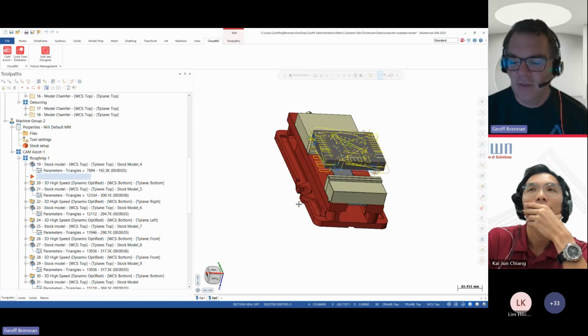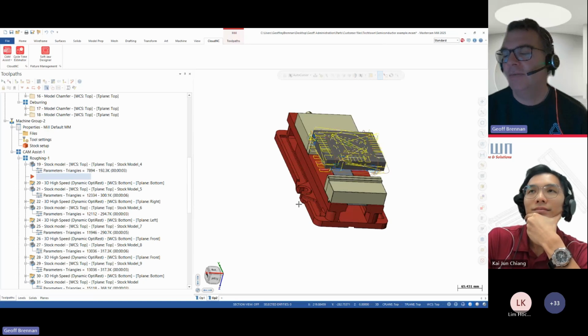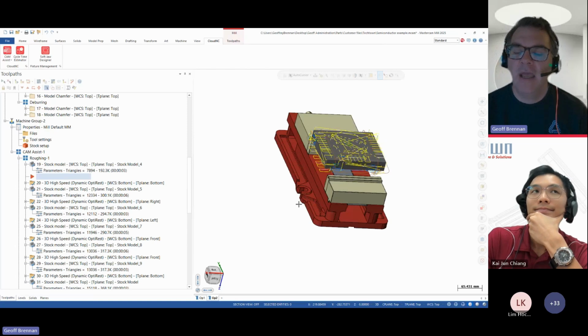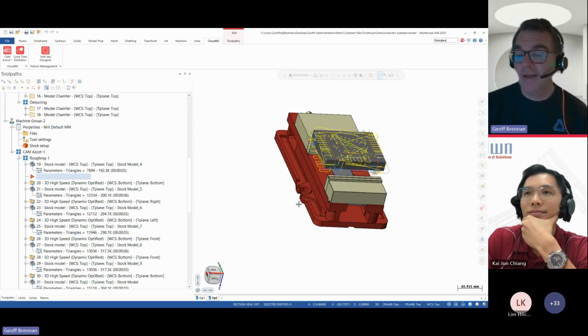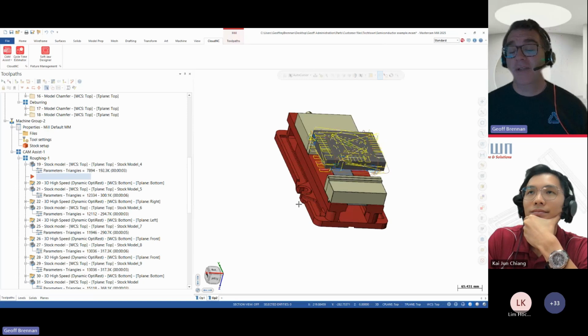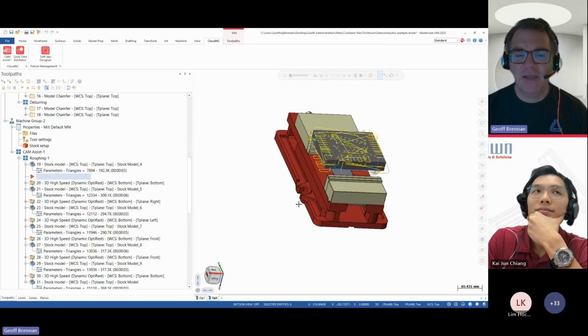But in terms of the size that CAM Assist can handle, the dimensional constraints in the computational space are a bit limited to sort of 0.5 meter by 0.5 meter in X and Y, and we can't put a hard number on that so much because it'll depend on the corresponding tool library. Of course, if you had a very large part full of complex geometry and you were using a very small tool set, you can imagine that the computational curve is going to be quite extreme. And so we could get some timeouts on the calculation from that side of things.